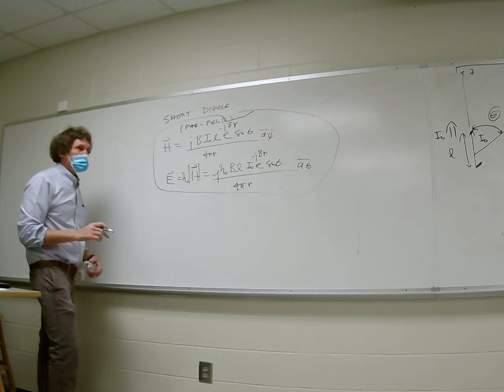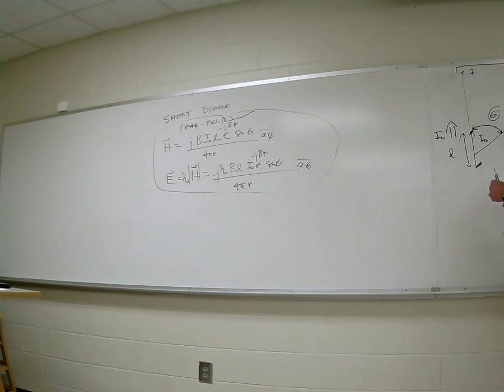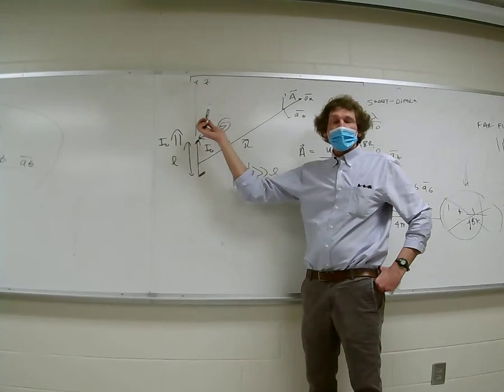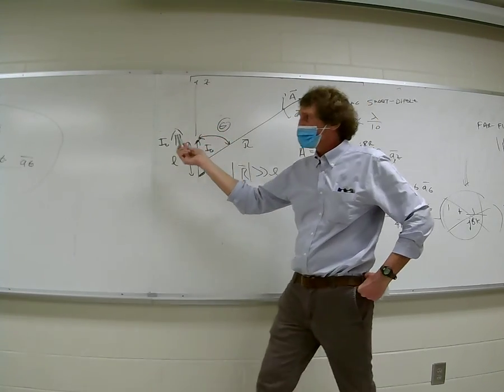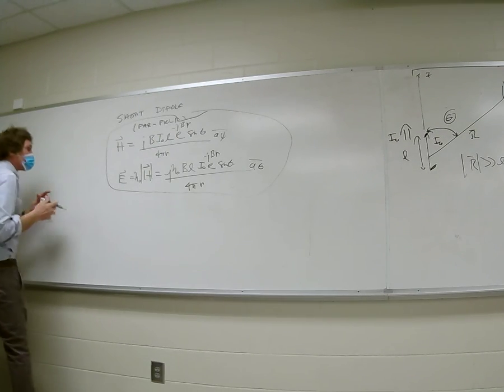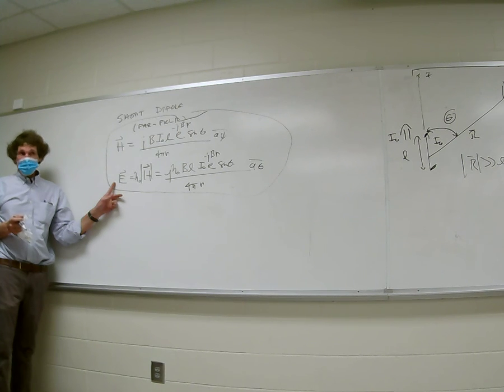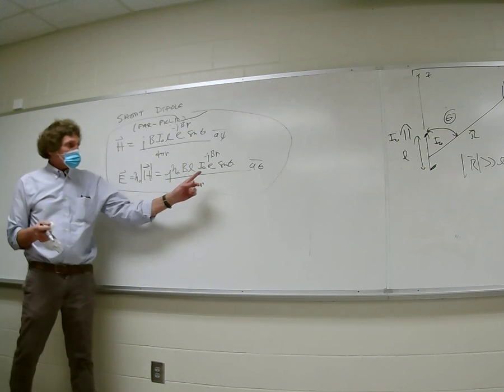Let me just take a moment and mention some stuff about that. I'm over already. But we're assuming these dipoles are aligned on the z-axis. Do y'all follow me on that? Can anybody tell me what would happen? I look at that field pattern. I can take a look at the power pattern by just squaring this, right? And dividing it by 2 eta naught, multiplying by 1/2 divided by eta naught. That would be the propagating power density, wouldn't it, class? And we could actually plot that. It would be a sine squared.